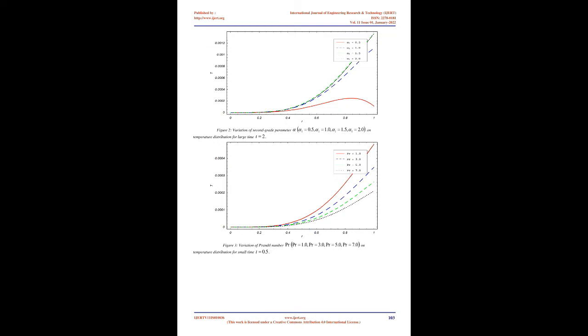The first mathematical model for unsteady third-grade fluid was presented by Akbarzadeh et al., 2016. In their model, the unsteady magnetohydrodynamic, MHD, blood flow through porous arteries with the influence of externally applied body acceleration and pressure gradient was studied. Blood is considered as a third-grade non-Newtonian fluid. The Homotopy Perturbation Method, HPM, was employed to solve the problem of non-Newtonian fluid flow for various flow models.